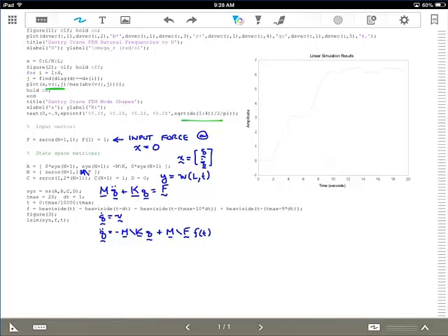And so this input F is just basically a square pulse, looks like this, where this area here is the same as that area. So we'd expect that you basically hit it with a pulse to get it going. It's swinging, it's translating and swinging, and then you hit it with a second pulse to decelerate it and stop.